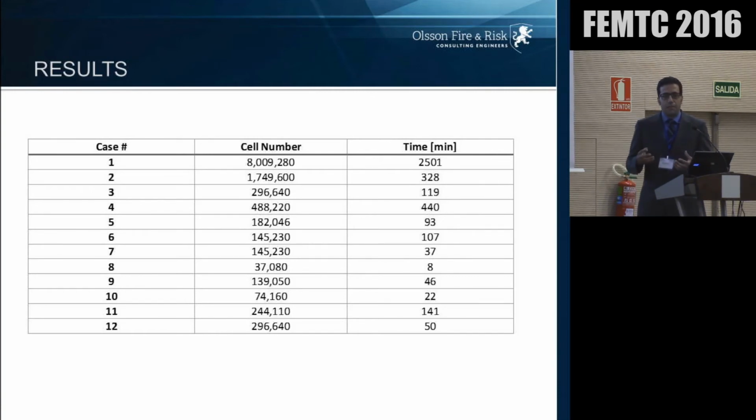You will find that maybe using coarser mesh with less accurate turbulence model, you'll achieve much better answers compared to a very accurate elite turbulence model with a coarse mesh. So it is engineering judgment.